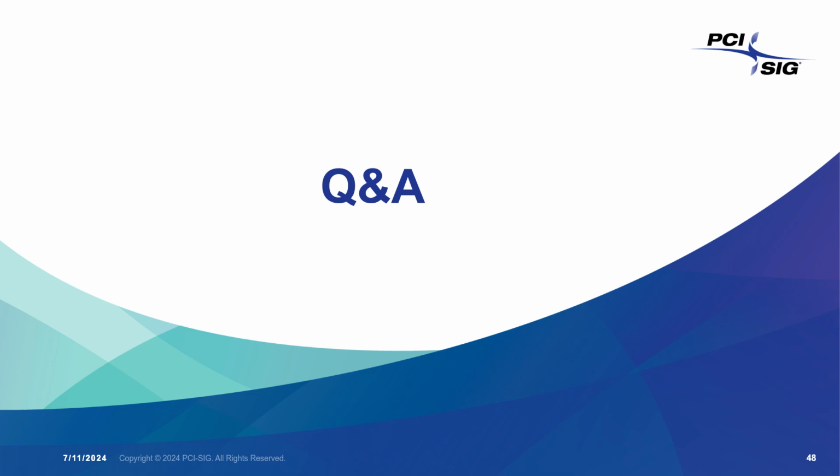I agree. Sam, your assessment? Okay, great. Our next question is, what is the projected channel loss budget for the PCIe 7.0 specification? Channel loss budget means die pad to die pad. It's minus 36 dB at 32 gigahertz.